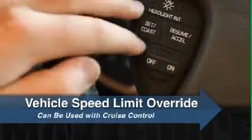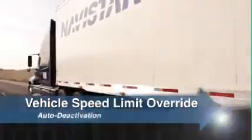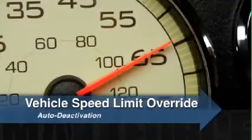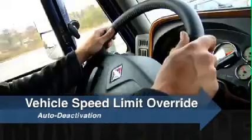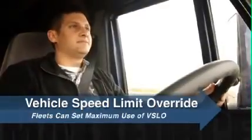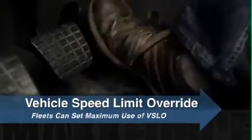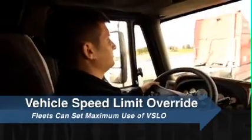VSLO can be engaged while cruise is enabled, but VSLO operation does not depend on cruise control. If the vehicle speed drops below the normal accelerator vehicle speed limit, VSLO is automatically deactivated. Fleets can set the maximum amount of time, such as 30 minutes, that the VSLO can be used within a 24-hour period.